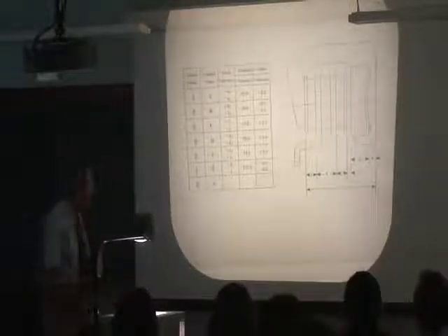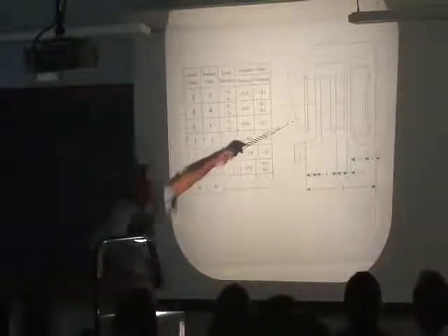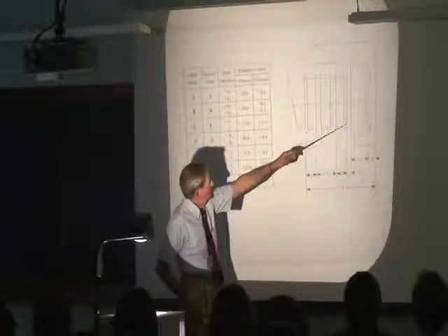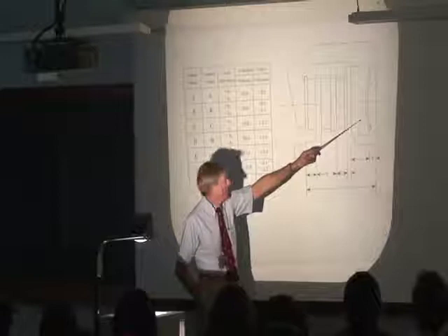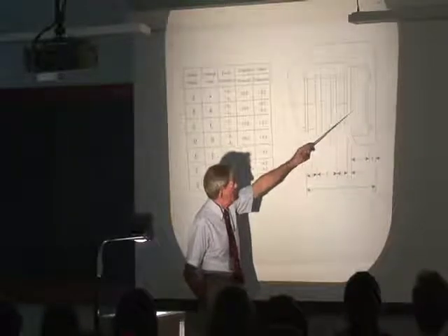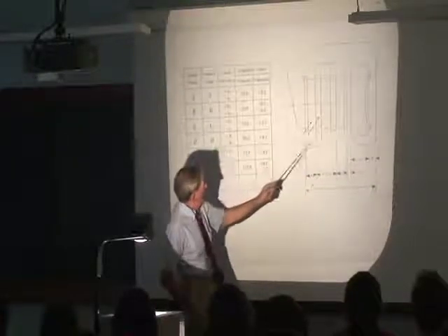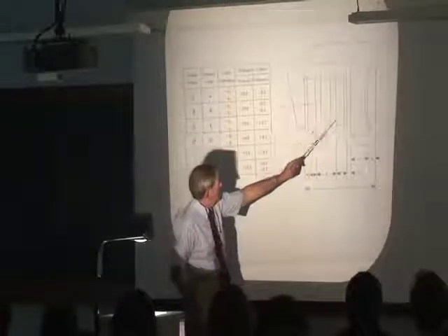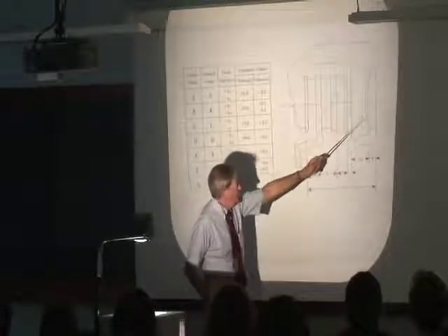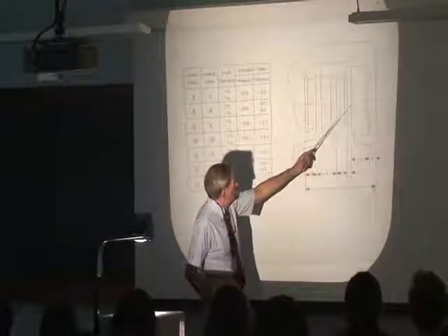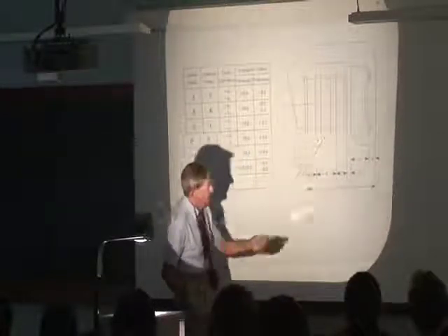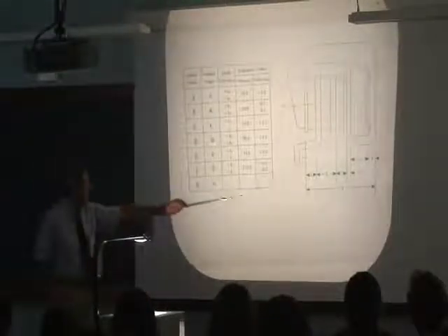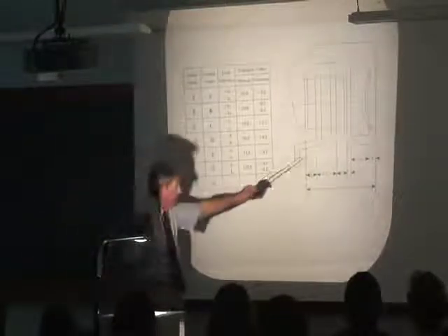Nice problem. This is a disc brake. And this is the frame of the disc brake. This is the actuator, which is either pneumatic or hydraulic. It presses this way. This is the rotor wheel. And these are the pads. So when you push the pedal, the actuator moves this way and pushes the pressure pads against the rotor. Okay. Now, there are these various components here.